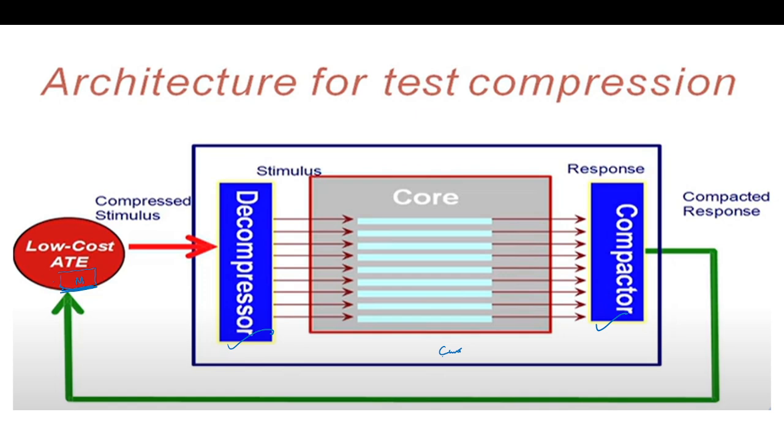Core based designs means say this core is a netlist. So each core we obtain from different vendors, and we integrate all the cores to form a SoC. So every core is tested independently. So the core vendor will provide a set of test patterns, because the core vendor may not know with which other components it is going to operate.